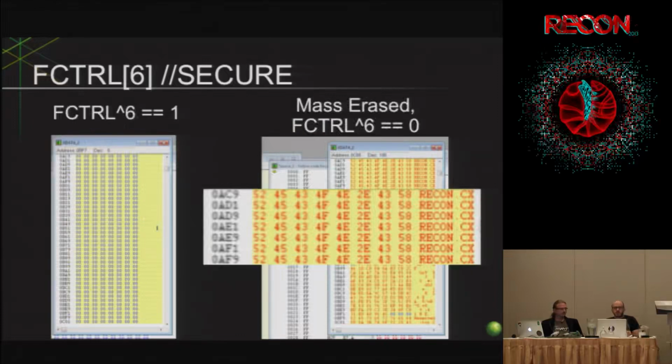So here's just a little picture of that. If you set it, the one on the left gives you all zeros. It's saying, hey, there's no data here, I can't give you anything. But as soon as you do a flash erase and do a reset, all that data is still there. That's important to remember, because what will often happen in encryption implementations is that they'll pick up data out of a read-only location, like code, and grab, say, encryption keys from there, and copy them into RAM.